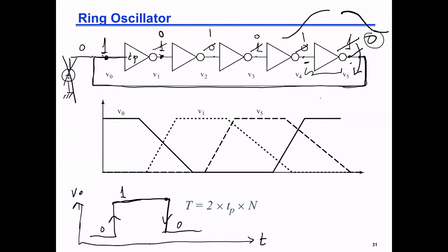It's not decreasing gradually because of the short circuit. It's decreasing gradually because it is the output of an inverter that has some time constant embedded in it. This is because of the behavior of the circuit. They will all be like this: when it rises it rises slowly, and when it falls it falls slowly. There is no direct flipping. Okay, deal, thank you.